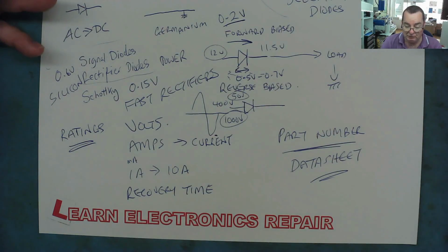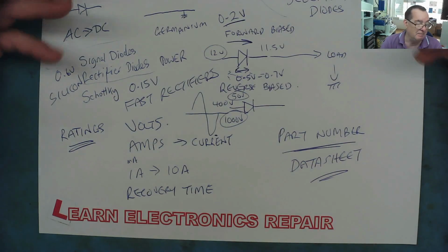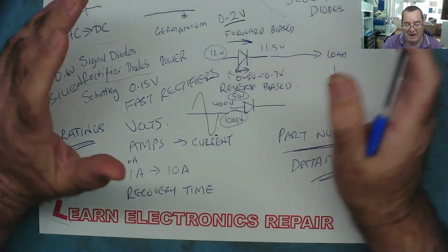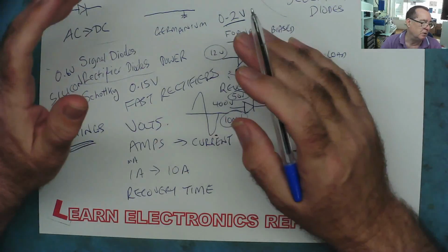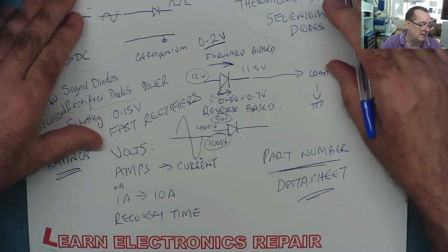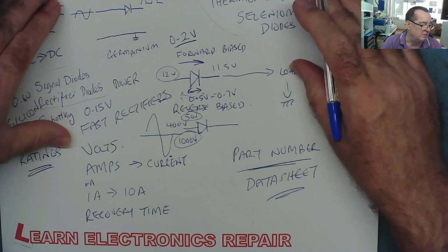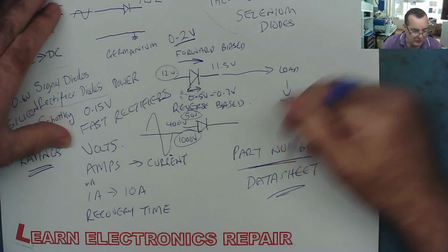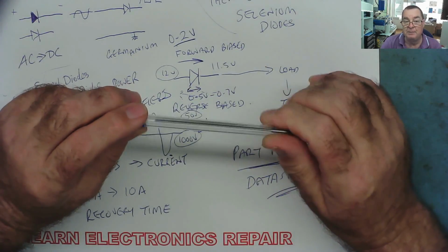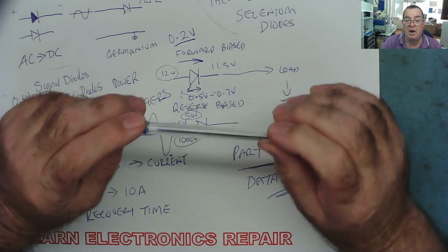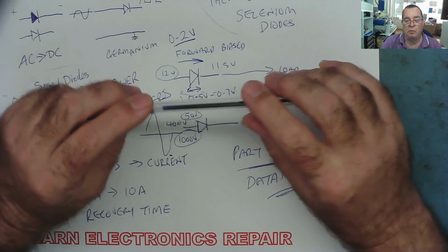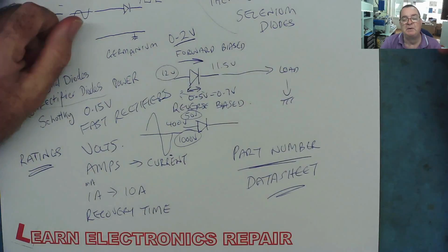For instance, on the secondary of a switch mode power supply, the rectifier diodes will be Schottky because they need to switch very rapidly between conducting and not conducting. The upshot of all this is that apart from in low frequency and mains frequency circuits, you need to replace the diode with a proper equivalent, one that's equivalent in the switching speed as well.